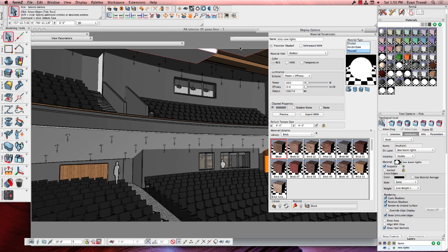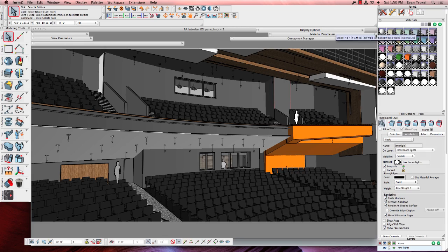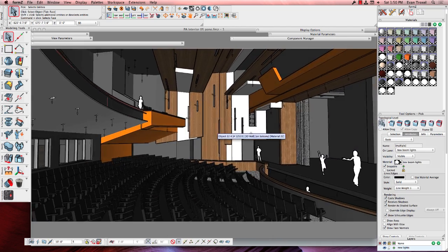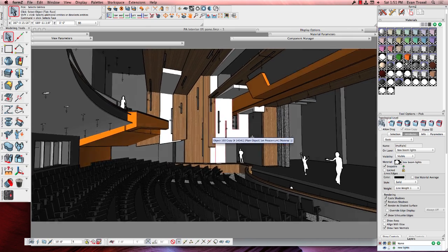And so everywhere that I have a different set of lights that I want to be able to control intensity later, I just duplicate the material, rename it, and apply it to that emitter geometry. And again, the reason I do that is so that I can go back in multi-light, and I'll get more into that in probably a future video, but I can control the lighting after I've done the rendering or during